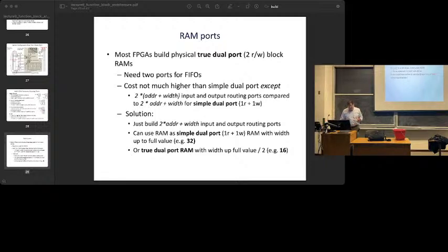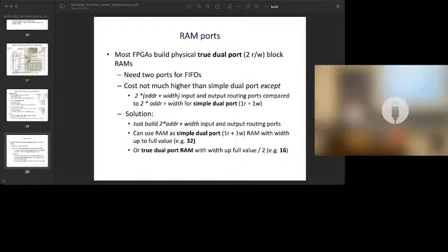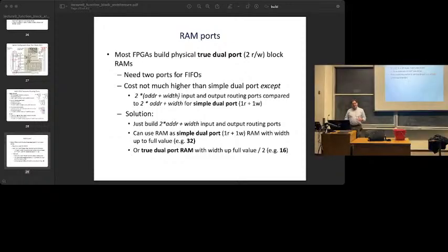It's kind of like a big shift register and a special write circuitry. We can't use that if we just want to write to one lookup table, which is what we need if we want to use this as a RAM. Like we can't reuse the configuration circuitry because we can't just start reconfiguring the whole design because it'll go crazy. So we're going to have to add something to it. And the question is, is it worthwhile or not?